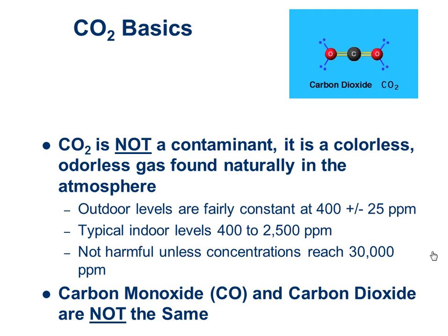People breathe in oxygen and exhale CO2. Plants, if you will, breathe CO2, if you want to say that, and exhale oxygen. That's probably the cleanest way to say it. People exhale CO2, plants inhale or absorb CO2. But you have to get to pretty high levels, around 30 to 40,000 parts per million, for it to be harmful to people. And inside most spaces, when you measure it with a meter, you're going to find most spaces will be between 500 parts per million and, say, 1,500 parts per million.